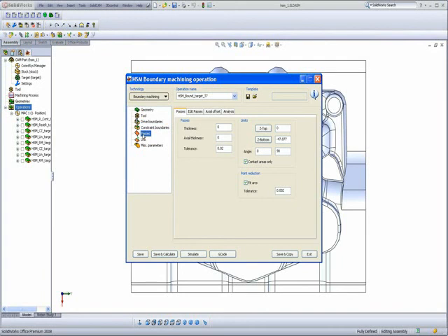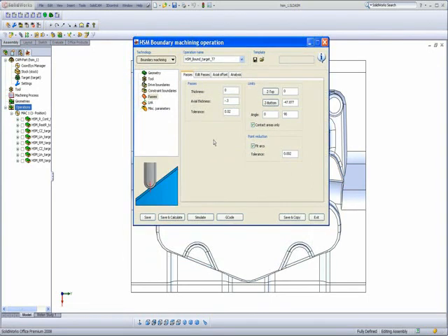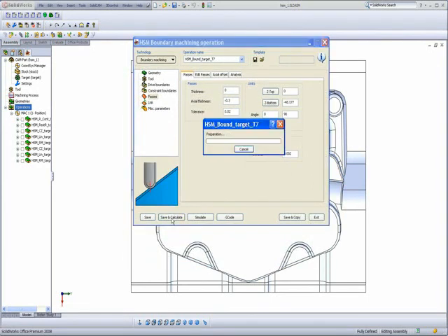In my passes area, if I leave it the way it is, nothing will actually happen. The tool would actually just go down and just run along the exact edge. But I want to give it a little bit of a chamfer. So I want it to actually gouge slightly into the part. So what I'll do is I'll make an axial thickness of minus 0.3 millimeters. This will allow the tool to actually go further down into the part itself. I'll simply do save and calculate.